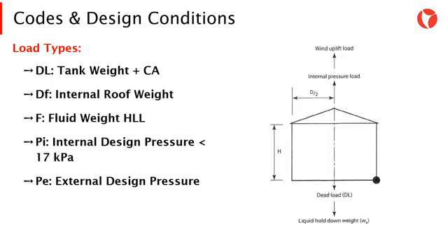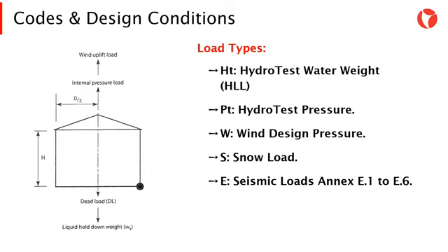Due to the large quantities of product that could be stored in this type of equipment, load definition is one of the fundamental aspects to be evaluated prior to any development. The loads that generally govern the design of storage tanks are the operating weight of the fluid, seismic loads, and the wind pressure, these two last conditions depending on the site.